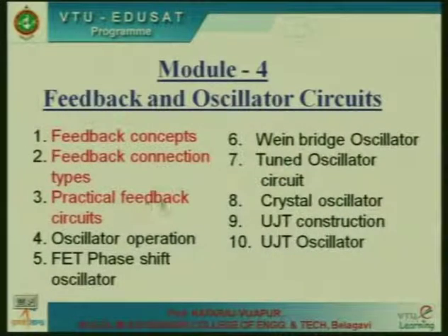We had discussed an example of a voltage series feedback amplifier by making use of an op amp as well as a FET circuit. We had started actually with the emitter follower as an example of voltage series feedback. So, we will continue with that.